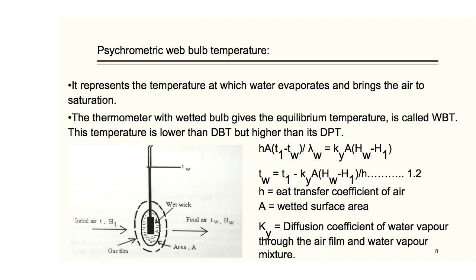So we have seen that when the outgoing air becomes completely saturated, using the psychrometric wet bulb temperature, then this temperature would be equal to the adiabatic wet bulb temperature. So we can compare these two equations at the saturation limit, and we find the Lewis number, etc. This is higher study.